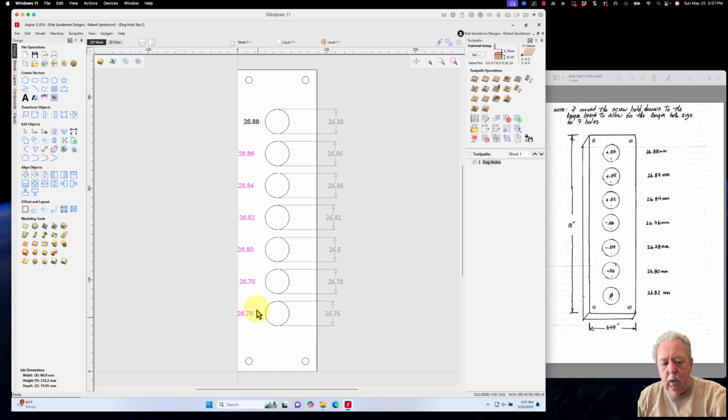So I'm going to grab all those by bringing a square, taking my cursor and moving it all the way around them, grabbing them all. Notice I didn't grab this one because this is the one I'm going to line up to. Hit the Shift key and grab it last. And now I'm going to use this so it centers horizontally on the last vector. So now they're all aligned in this direction. That's what I'm doing, and I think that will work out pretty well.